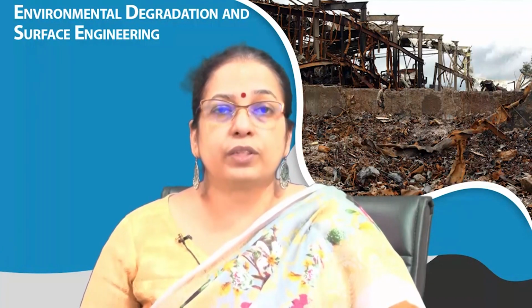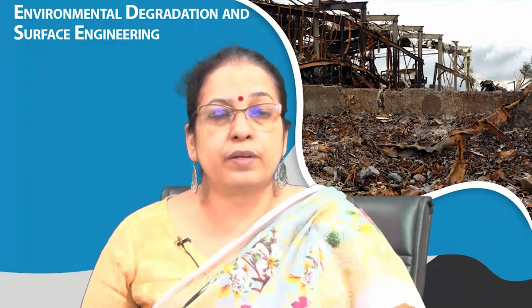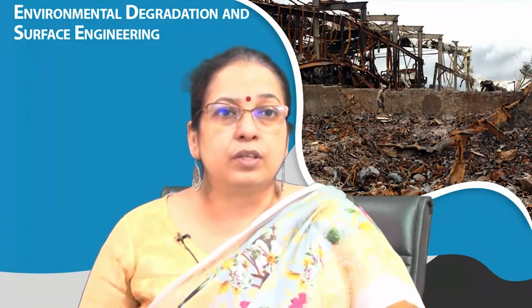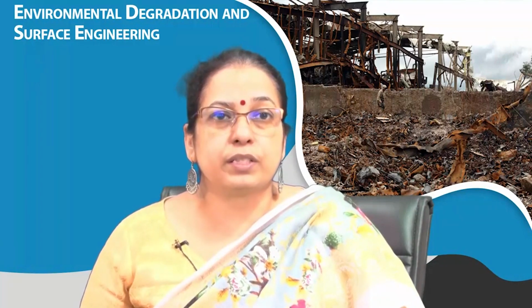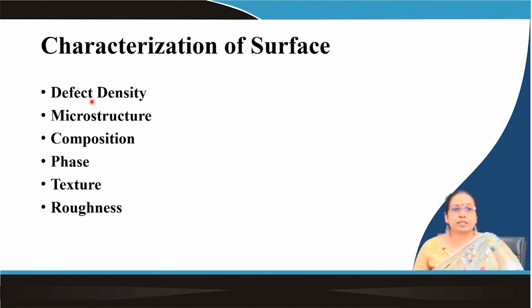Whenever we talk about characterization, we discuss those tools which are used to know the characteristics of the surface. The surface characteristics are defect density, microstructure and composition of the surface, phase, texture of the surface microstructure, the roughness of the surface, and also the state of stress, and the residual stress which is retained on the surface after different surface treatment or different processing.